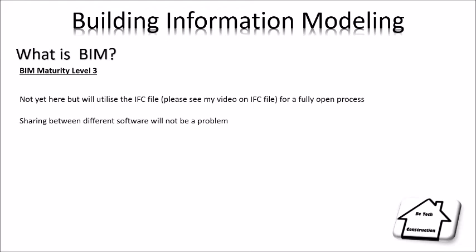At the moment we do have the problem of, if we have many different companies using different BIM software, they're not necessarily compatible. Just because it's BIM software doesn't mean that you can open a model made in Revit. You can't open that model in ArchiCAD, Graphisoft ArchiCAD. You can do something called export to an IFC, which will give you a version of the original, but it can't be edited or worked from. It's a reference file only.